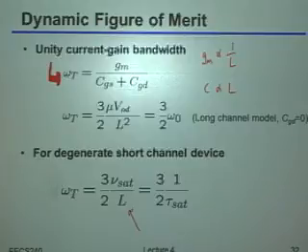Yeah, gm, right? Because basically the only reason gm was changing with length was that effectively the velocity of the carriers was going up. If you're completely velocity saturated, that's not going to help you any. So it's really only from the capacitance now. This has an interesting physical interpretation: your maximum frequency is related to how fast the carrier can get from the drain to the source, and that's set by the channel length. But indeed, that's why you get this regime where, much like with the drain current, the omega t will be somewhere between linear and quadratic on the channel length.